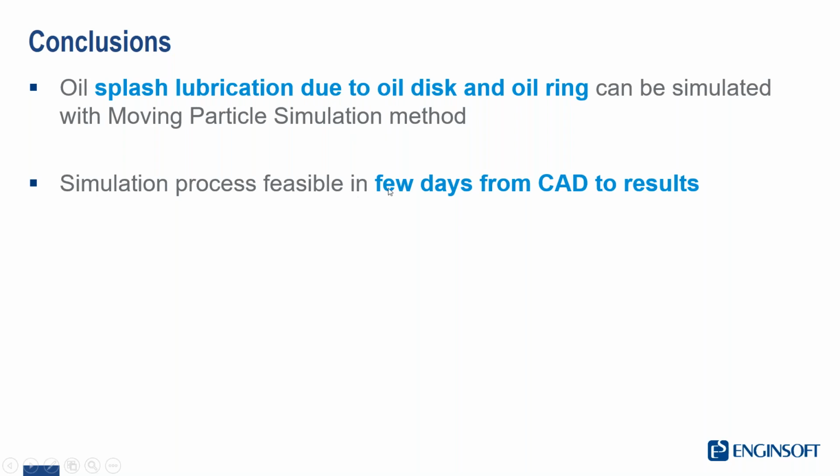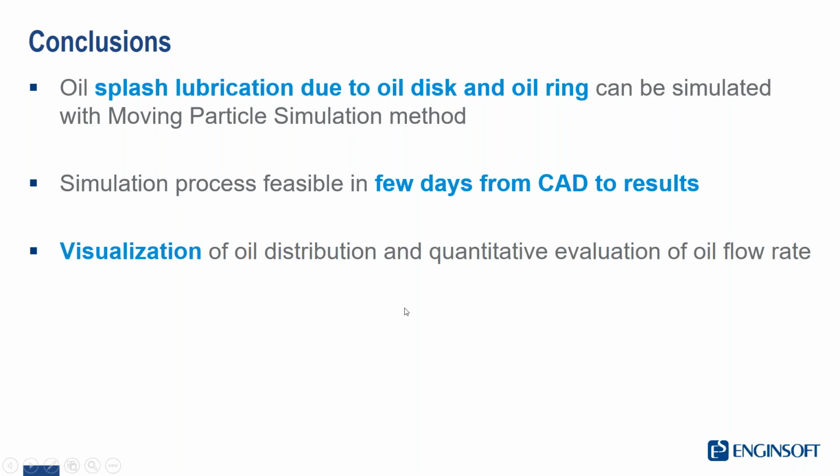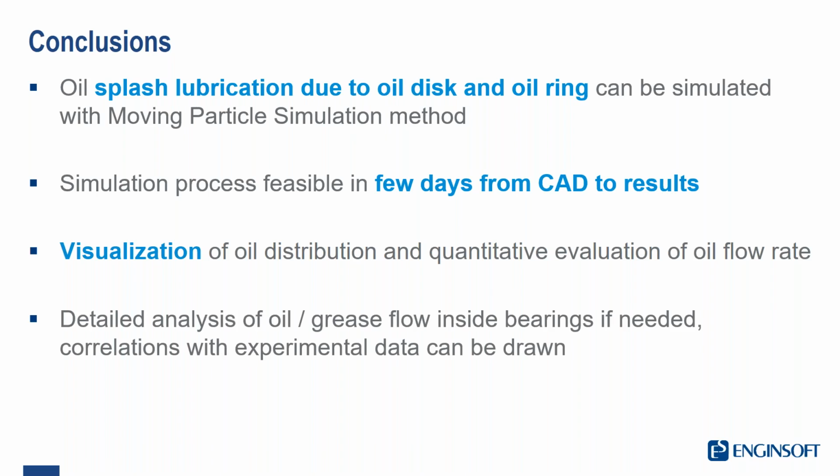And as I mentioned, with ParticleWorks, we can fit our simulation process inside the very demanding design schedule and production timing. We visualized the oil distribution, and we gave some quantitative evaluation of the flow rate and the lubrication efficiency. And we also showed how we could correlate the results we got with some experimental setup.